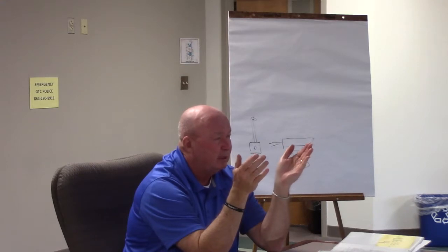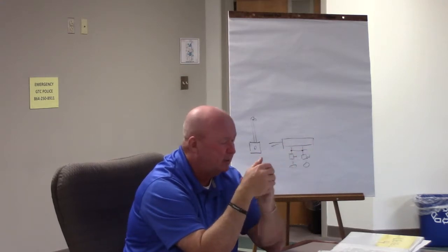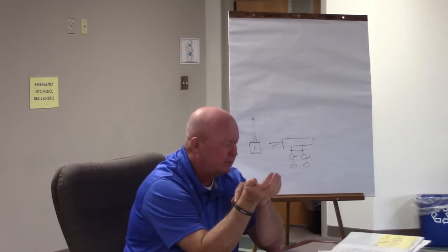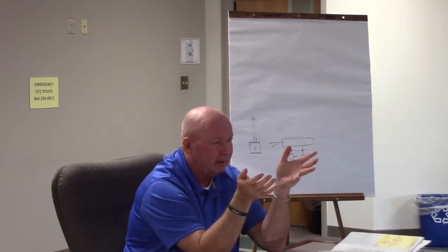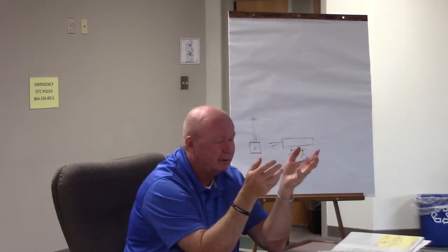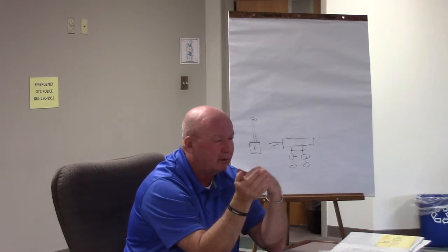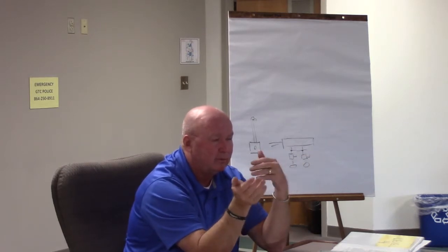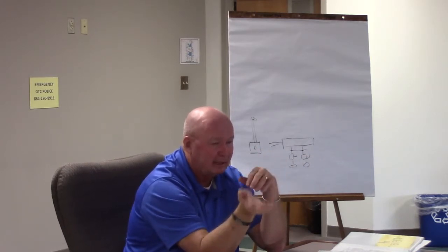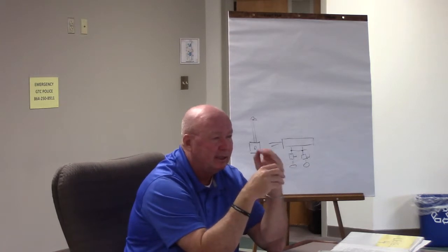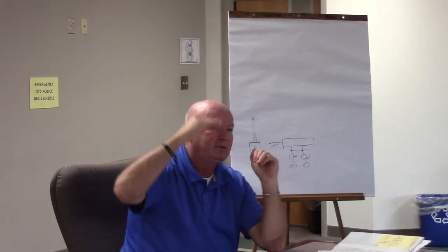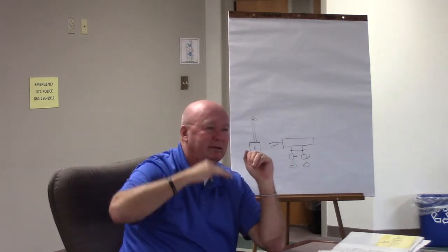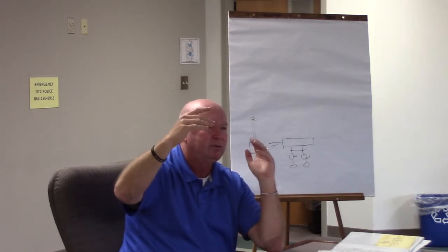Copper, when we're doing voltage drop, like when we're doing calculations, one of the things we have to put in there is a K. And so it's called the constant. 12.9 for copper, aluminum is a different number. And it does have to deal with resistance because 12.9 in copper, whereas aluminum is higher. It's like 21.3 or 21.2.